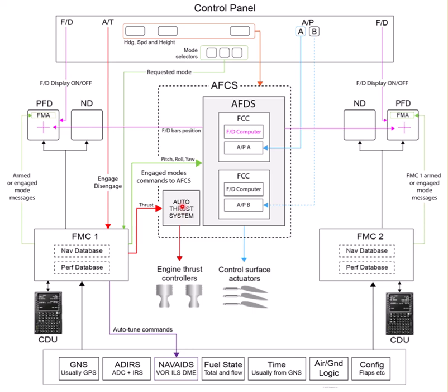In flight level change, the auto thrust system will select a climb thrust, and the autopilot will look to see what speed I've selected in this window, and it will fly that speed. So this is really safe climbing and descending, because if the autopilot is controlling the speed in pitch, I can't overspeed or stall, because the aircraft won't allow that to happen.